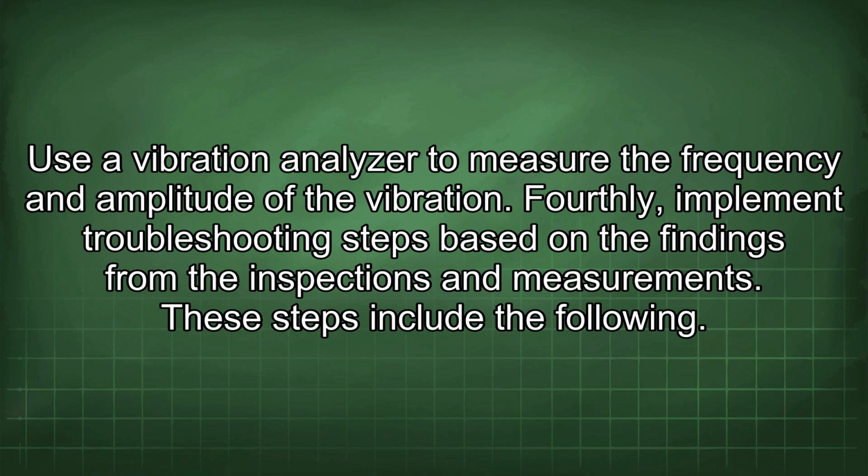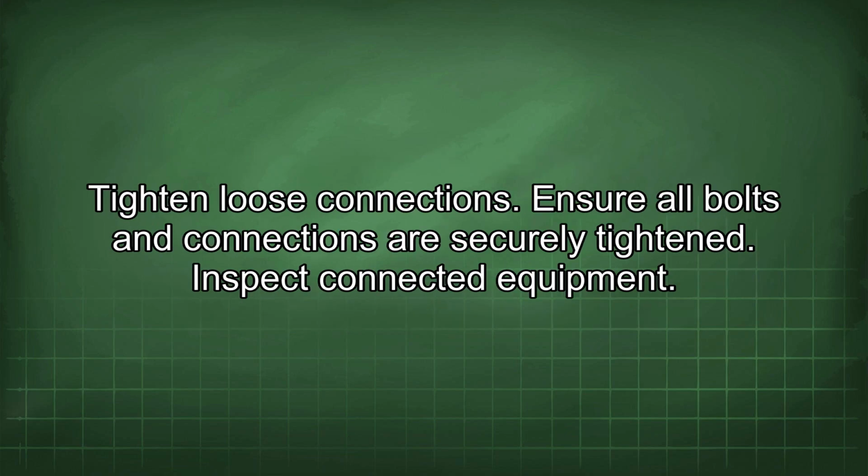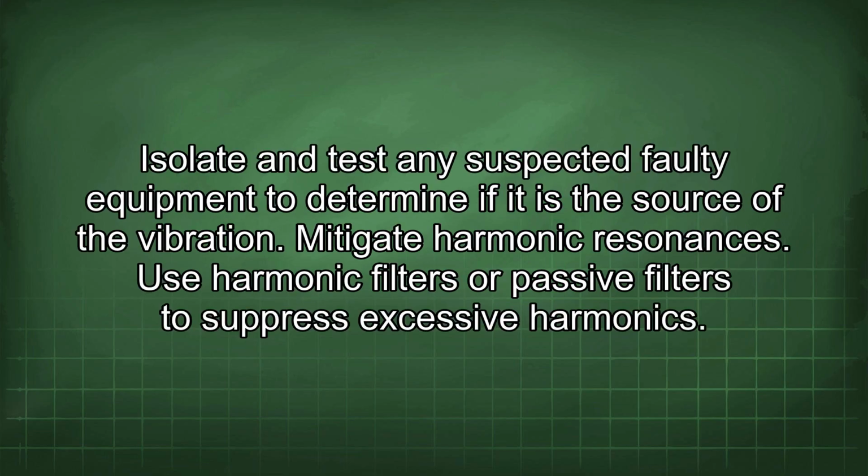Fourthly, implement troubleshooting steps based on the findings from the inspections and measurements. These steps include the following. Tighten loose connections. Ensure all bolts and connections are securely tightened. Inspect connected equipment. Isolate and test any suspected faulty equipment to determine if it is the source of the vibration.